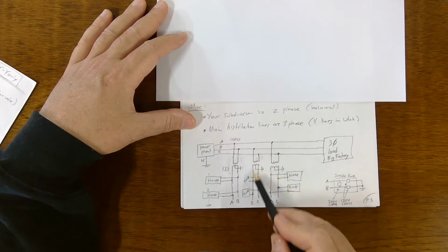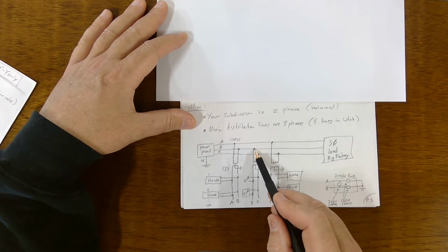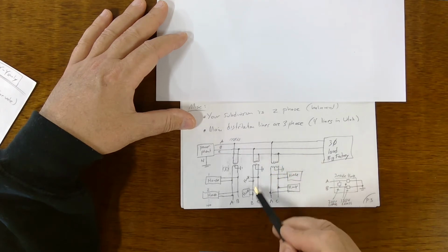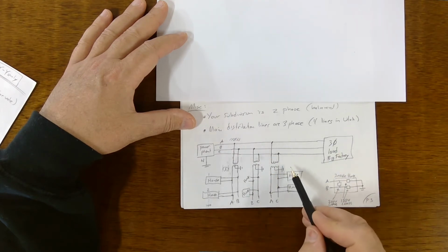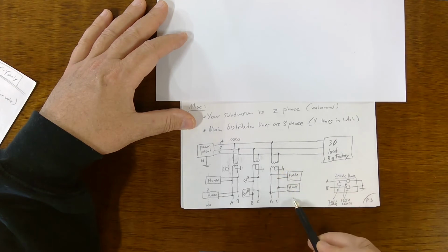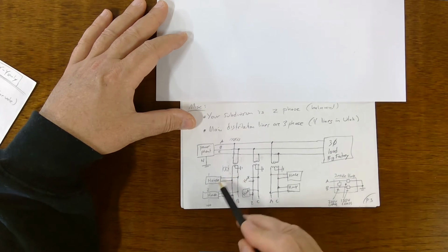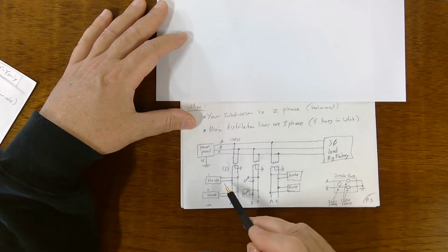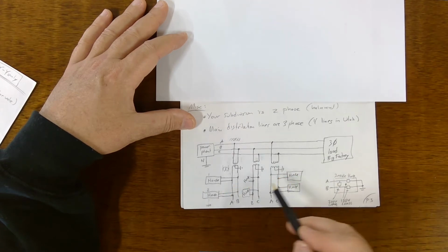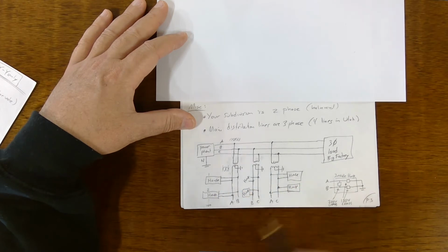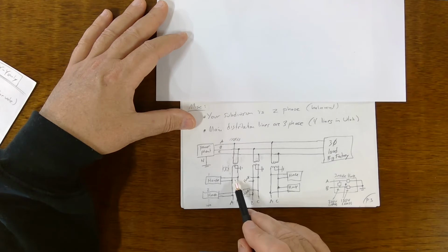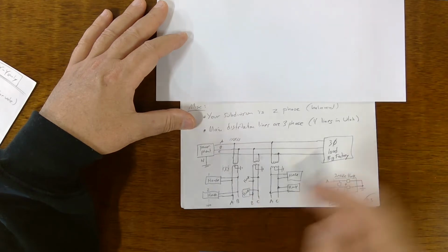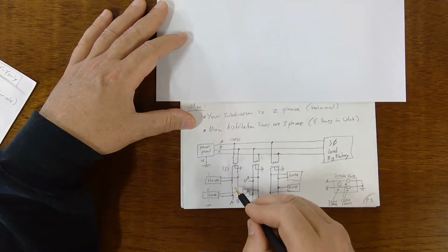Yeah, and then another subdivision of 100 houses may pull off of BC phase, and there could be 100 houses there, and then another subdivision of 100 houses could pull off of AC phase. So there's 100 houses here, 100 houses here, 100 houses here, and on average, the people in those houses are doing the same things at any given time, so the loads are balanced. Okay, so this is what I just did right here, by the way, is a delta connected load.